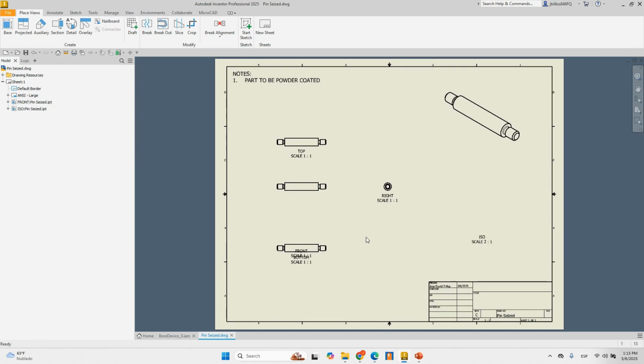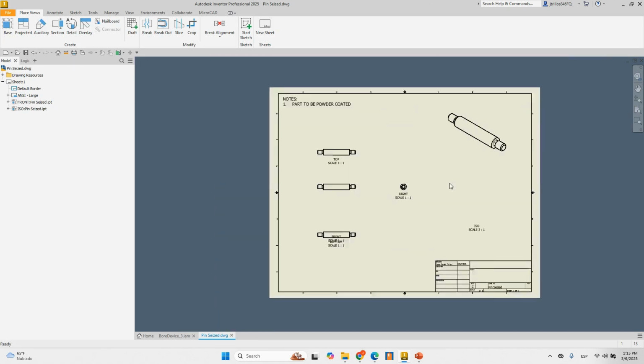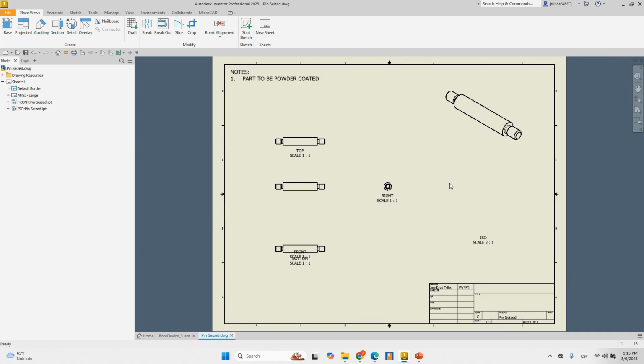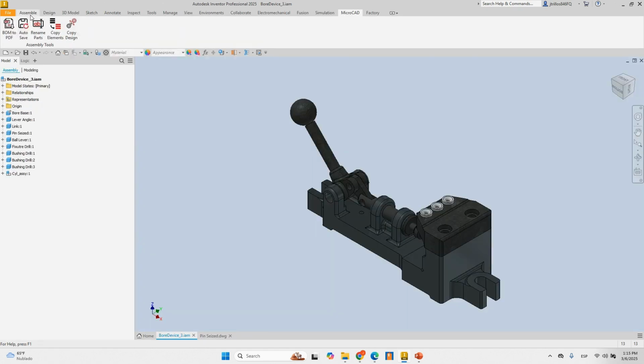There are some tools in Inventor already that can let you create a template for creating these drawings automatically, so that might be something that we can integrate, specifying a template file for creating the actual file, and plus summing this to the BOM to PDFs, so we can export those PDFs in one single go.